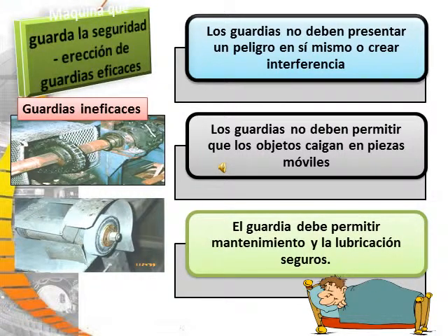Guards must not present a hazard in themselves or create interference. They must not allow objects to fall into moving parts, and the guard should allow safe maintenance and lubrication of the machine.